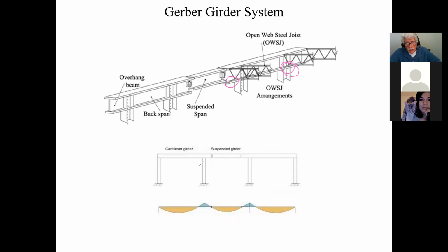So like I said, if this beam here happened to be just going from here to here, from there to there, like a simply supported beam, the moment would end up looking like this. And by having the overhang, I take part of that moment and I bring it up here. So therefore my MF gets reduced. And since my MF gets reduced, I can reduce the size of the beam that I need to get my MR. So that's what we're doing, okay?